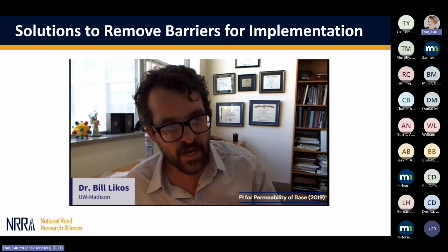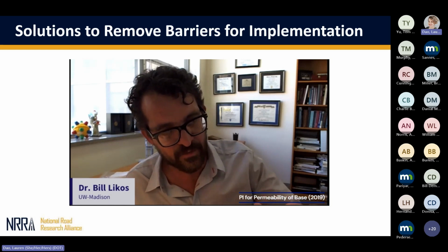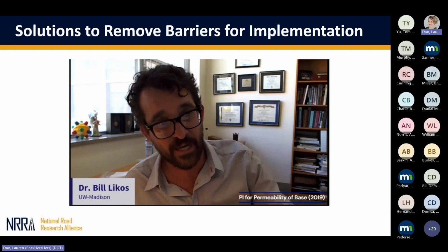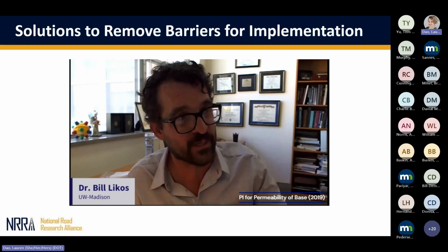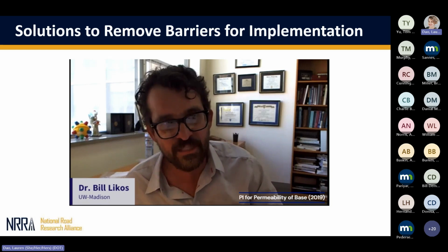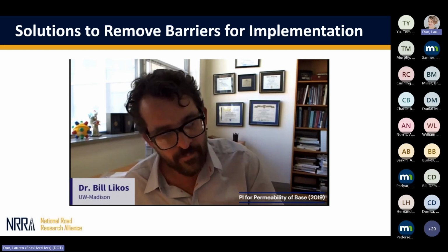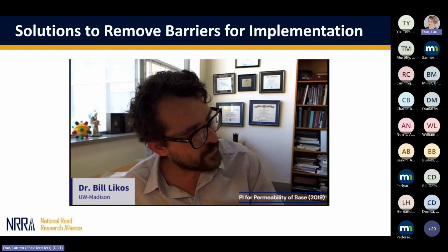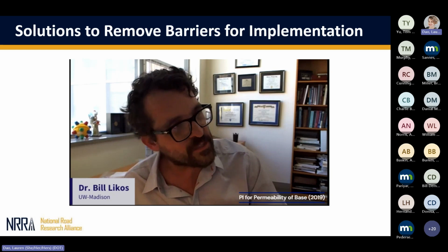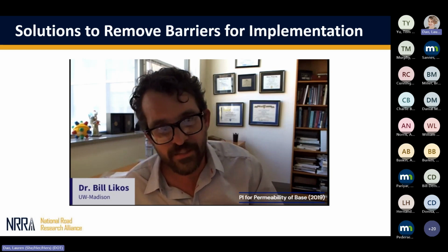I think holistic consideration of, again, in terms of pavement drainage, the pavement surface, the subsurface, the subgrade, and the environment. This is all one big sort of circle, and all of those things need to be included as a system to really get to a problem like this. I think that field measurements are important. The study that we did was focused entirely in the lab.